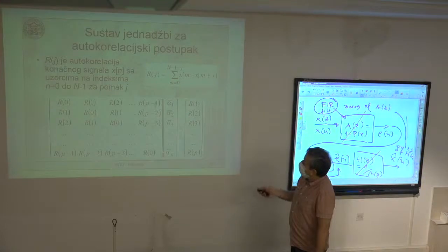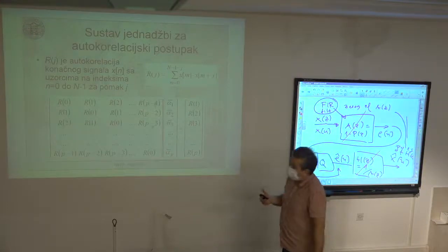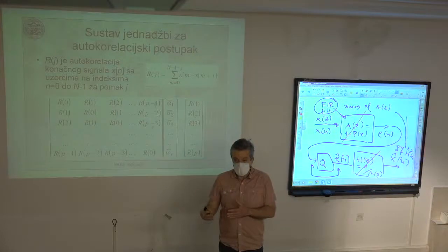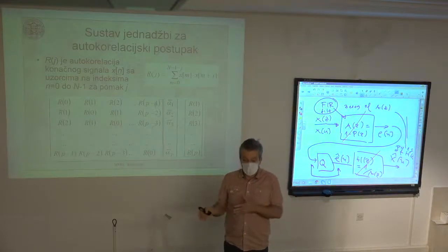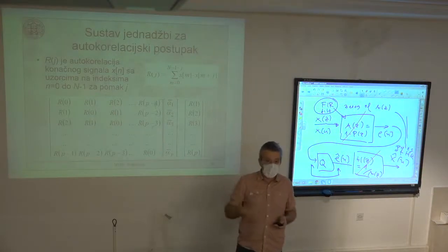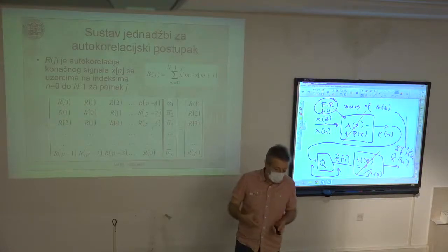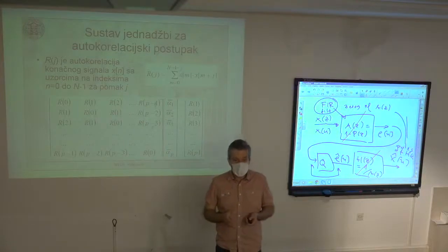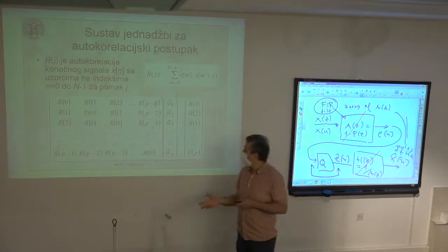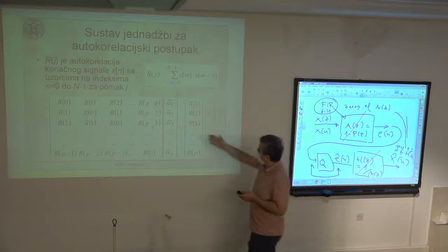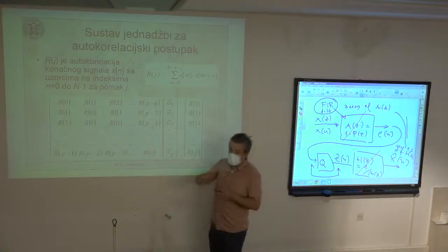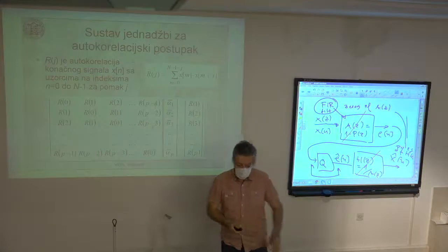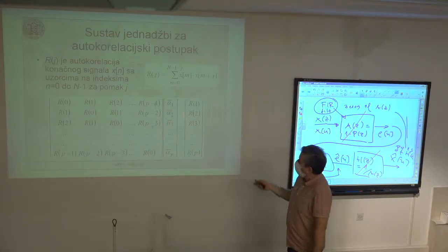And this information can be sent as side information from the transmitter to the receiver. So I simply adapt the predictor from time to time. For example, 50 times a second, I send new predictor coefficient values. I compute the optimal predictor, and I somehow transmit to the receiving side the optimal values for the predictor, alpha 1 to alpha p, for this part of the signal.